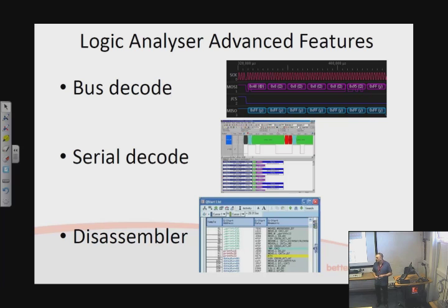We can load software into our logic analyzer which can decode that and extract the serial information by looking at the timing of the signal coming in. So you might only be using one logic analyzer input, but doing some quite sophisticated time-based decoding.